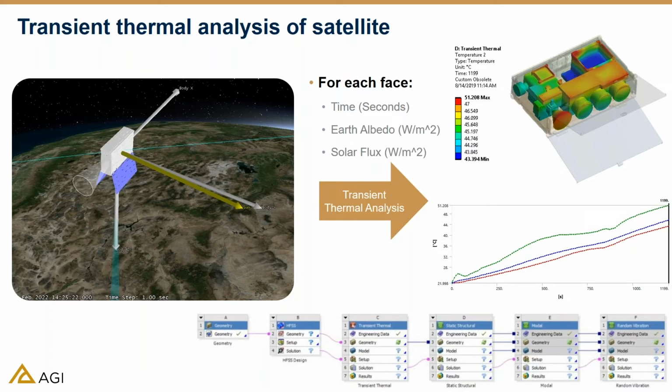performance within the satellite. I also want to mention that ANSYS Workbench is a multi-physics platform that can integrate different solvers together. For example, using the coupling analysis of ANSYS high-frequency electromagnetic field solver HFSS and the transient thermal solver in ANSYS Mechanical, ANSYS customers can simulate thermal buildups in external antennas and internal electronics to check if antennas are subjected to a potential risk of loss of efficiency and drifting of desired tune frequency.